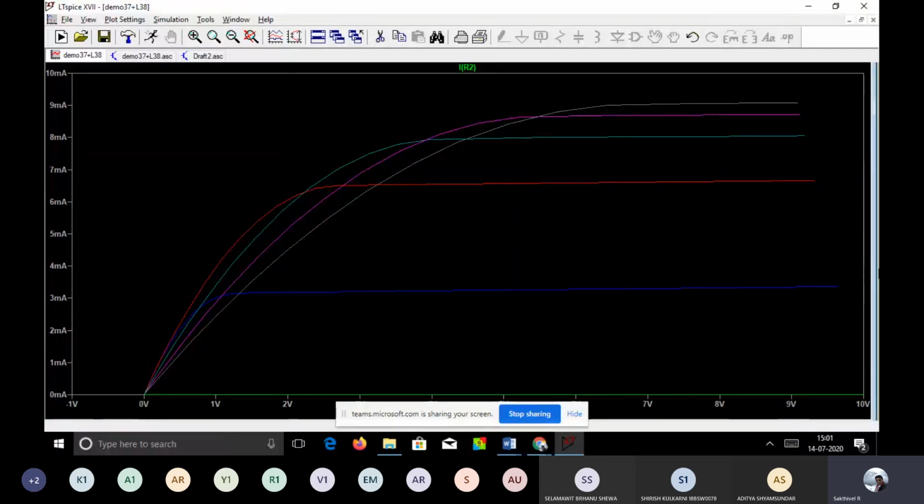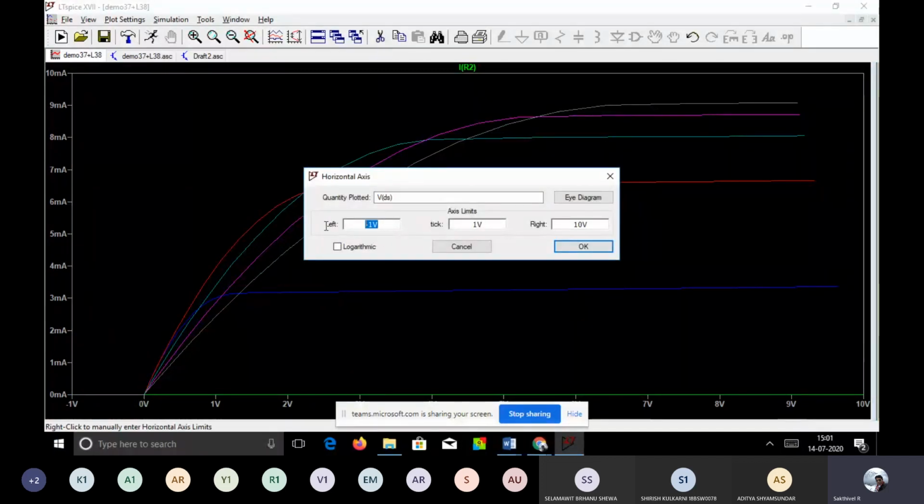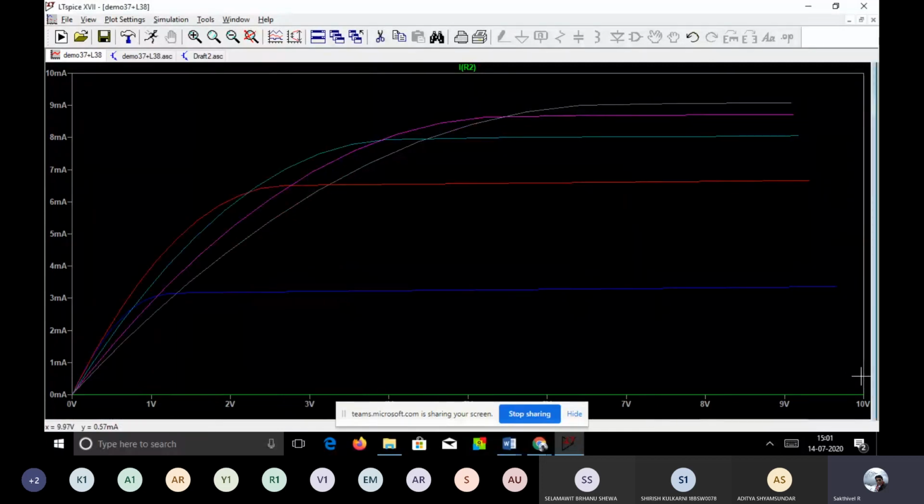Or any voltage less than that of, I believe the threshold voltage is 0.9 or something like that. I need to check the model file there. If it is less than that, the device will not switch on. Right? Now what you could see here is this is an extended version up to -1. In fact, you can even change that also. The left side you can make it as 0 volt, no issue. Now the graph will again start from this point. That's all. This is a simple IDS versus VDS graph for different values of VGS.